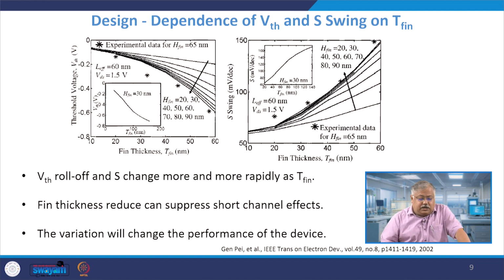Let us look now at the threshold voltage versus fin thickness. So that was before with H fin, and now this is with T fin, right. And as you can see, as expected, as the T fin increases, I would expect to see the increment in the value of your threshold voltage. And if you look at the subthreshold swing versus T-fin, again the same phenomena, it goes on increasing, right.